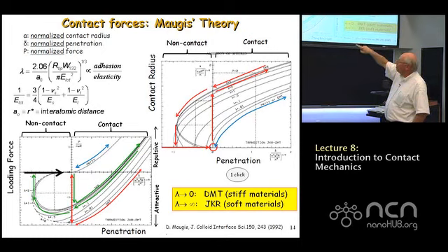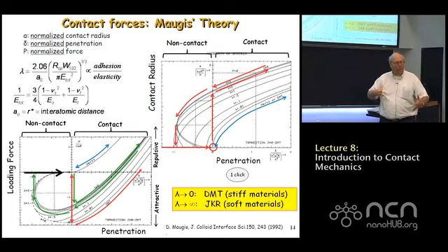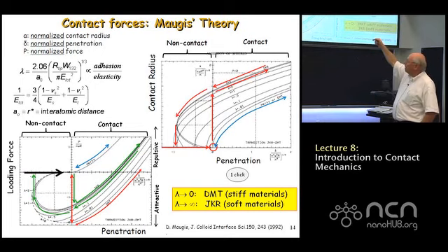As you then increase the penetration by increasing the force between the tip and the substrate, the contact radius increases. And then as you withdraw, as you pull the tip away from the substrate, the JKR model predicts that the radius of contact will not go to 0 in a reversible way, right?